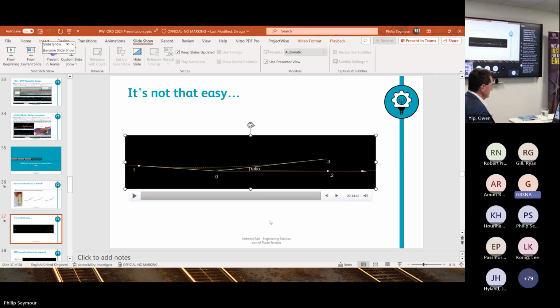So the white arms, 0.10, 0.2, 0.3 are arm length ratios. The green dash, not sure how well that communicates, is the turnout branch geometry. And what we're trying to show is that the S&C turnout branch geometrical elements have to converge at 0.3 correctly and coincidentally. So that's a very powerful visual that makes a lot of sense to myself.